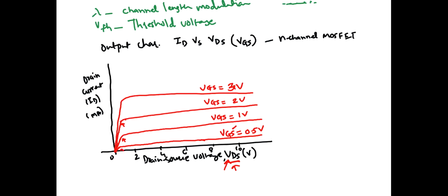Well, it is not easy to plot the curves by hand, but it's still understandable. So VGS is equal to 4 volt. So you see, for positive and increasing values of VGS, your current is increasing initially, and after that, your current is saturated.